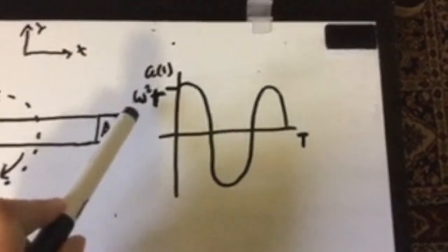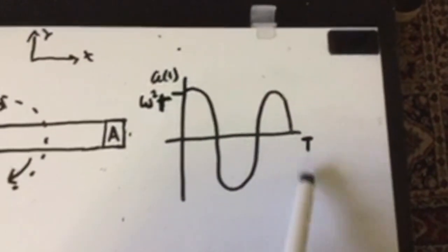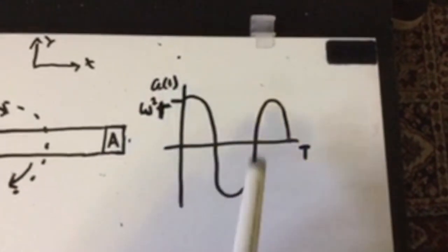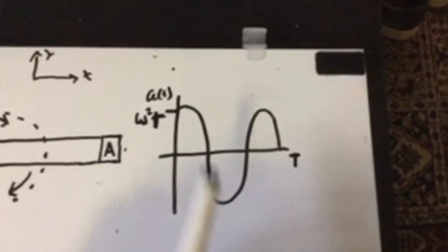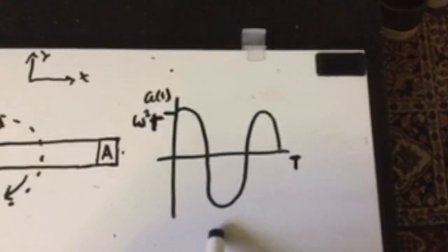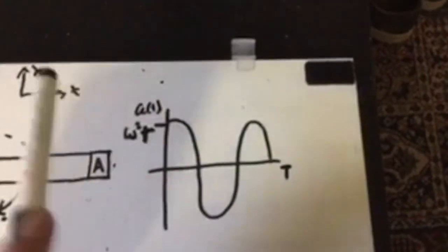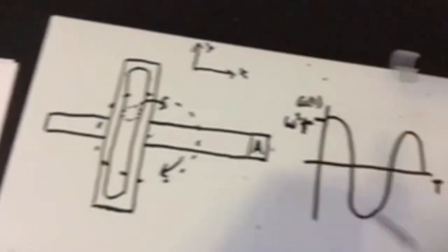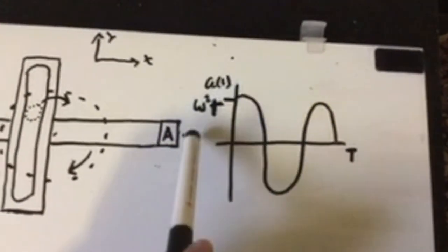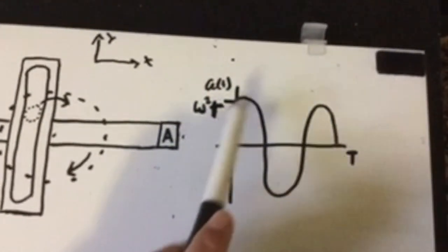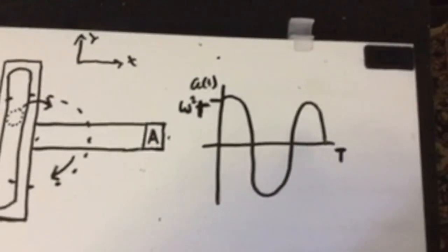As you can see here, the omega squared R in the acceleration times graph alternates, and the maximum acceleration is here at the peaks, both in the positive and in the negative acceleration due to the variation in the movement of this structure. Therefore, we have to find how to maximize and the values for omega and r that will let us make these peaks equal to 10 meters per second squared or greater.